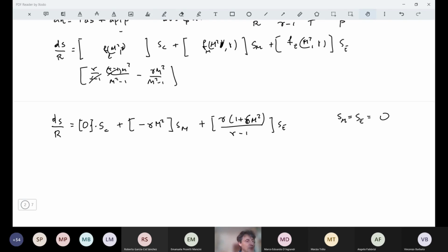So we have no friction, no heat or work addition, and no differences in terms of velocity and temperature in case we have mass addition or subtraction. So why could this change of entropy be important? We can translate it into a change of total pressure. That, of course, can be important in our applications because losing pressure means losing performance or, in general, additional costs of getting the desired pressure.